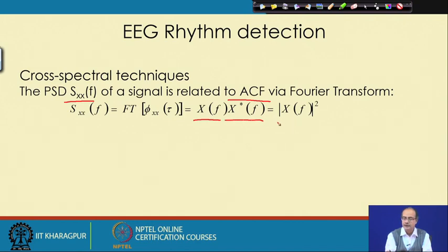In other words, we are looking at the amplitude spectrum, or the square of the amplitude at every frequency, because we want to know how much energy is there at a particular frequency. And for continuous spectra, the PSD is the best way to get that estimate.